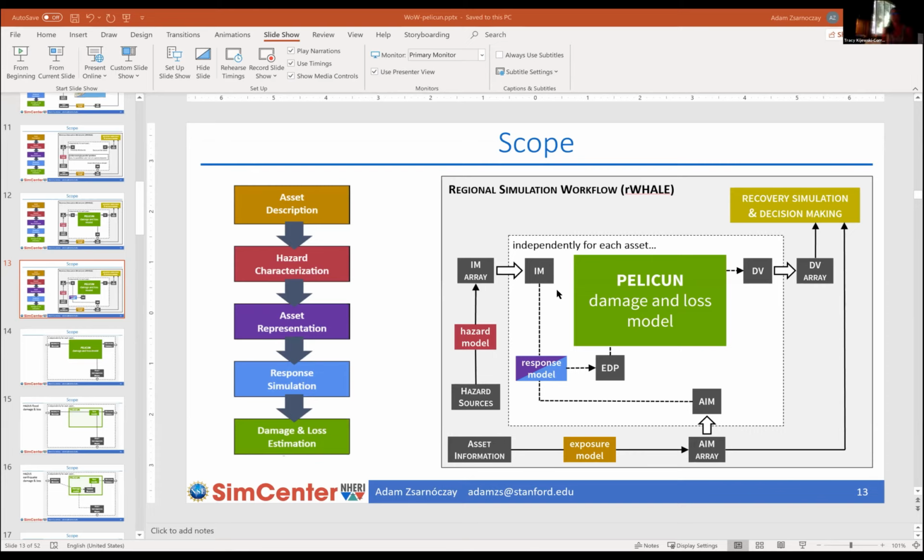Yeah, so what I would say right now, Mal, is that the way it's structured currently is that all the representations of the structure and the simulation of damage happen in an entirely computational manner. The pristine structure from the building inventory, no damage, is pushed through the simulation, exposed to the hazard intensity. Its corresponding level of response then results in some level of damage, and it moves through the workflow completely using computational simulation, and not mashing up any kind of actual damage that may have occurred in the event that you were trying to hindcast, let's say, performance based on some full-scale observations after an event.